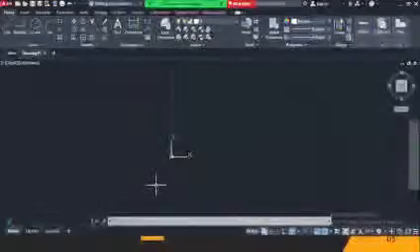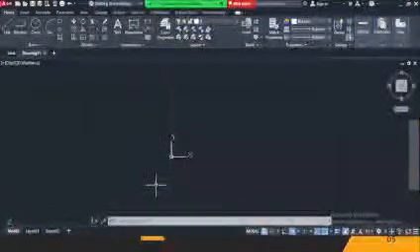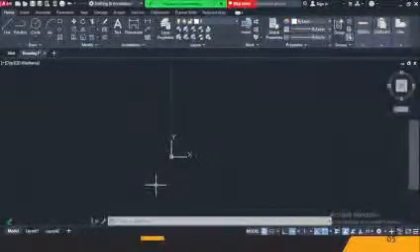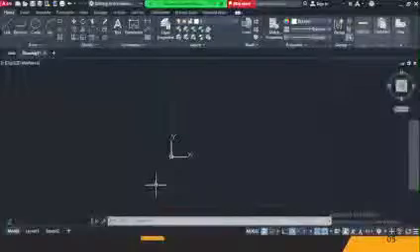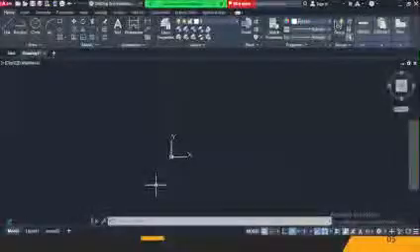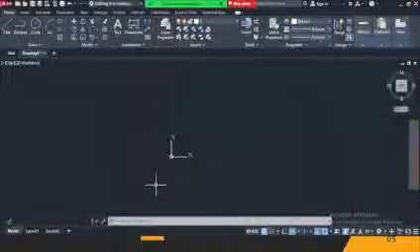If I'm drawing a building plan, and let's assume it's a one bedroom apartment, on one plot of land, maybe 100 by 50 meters, when I'm setting my limits, I will set my limits above 100, something around 150 to 200, because the highest I can go for my drawing is 100, because the plot plan is 100 by 50.